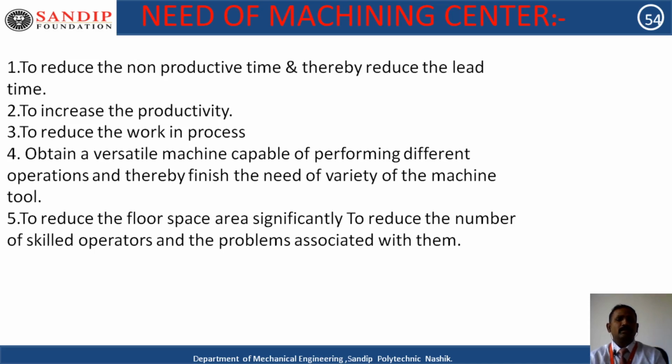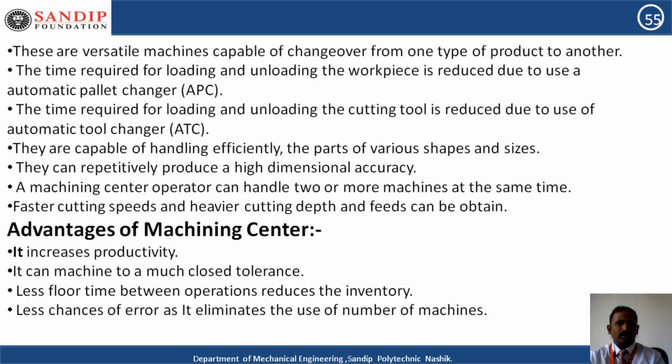To obtain a versatile machine capable of performing different operations and thereby eliminate the need for a variety of machine tools. To reduce the floor space significantly, to reduce the number of skilled operators and the problems associated with them. It requires skilled operators also. So that's the need of the machining center.